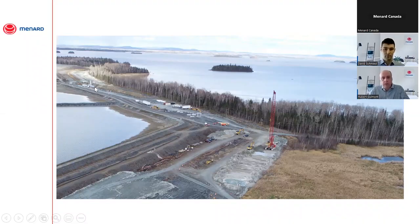Pumping distances can be up to, I'd say, 1 kilometer. That's a typical distance. Of course, as close as possible is always better. So the batch plant is there. You need to make sure that you have delivery routes for your cement trucks, and then you have a line. You pump through a line and down to the rig. Everything is instrumented, full-time monitoring of what's being installed, and that's it.